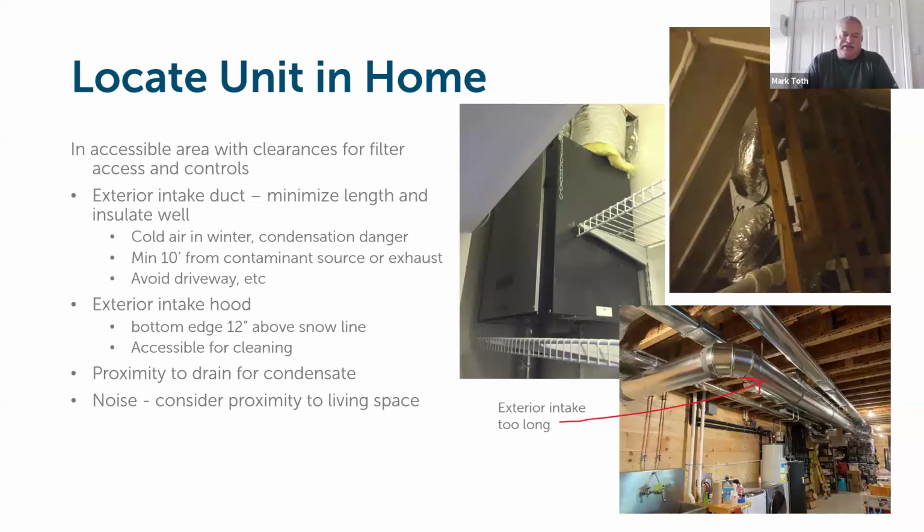Exterior intake duct, I mentioned a minute ago about insulating that. We're going to have pictures later to really get into that and talk about why that has to be insulated. Anyway, the biggest thing for locating in the home is to make sure you can get at it. Don't build it into somewhere where you can't get at it, back in some corner where no one can access it, because they do need to be serviced. Not often, but at least every 4, 5, 6 months, you're going to need to get in there and change or at least inspect the filters. So move ahead, Karen.